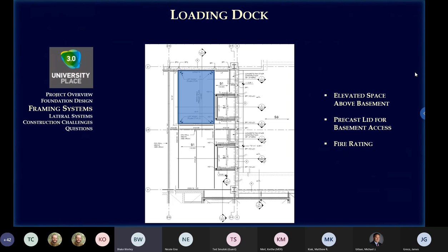And what we led to was basically sealing this with spray foam each time it would be removed. The detail was the plan was just to put the plank back and then seal with spray fireproofing. Otherwise, this joint was a trouble spot for any fireproofing.